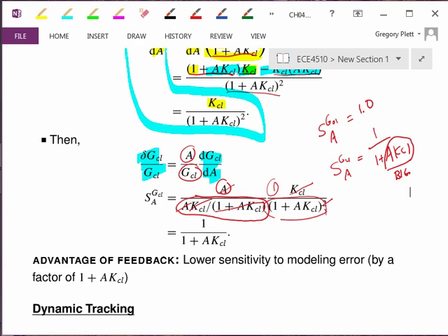Now, if you tune that open loop for one vehicle and you drive a different vehicle, then, oh my goodness, you're in for a wild ride. You're going to be going much faster or much slower than you thought. But because you've learned to use feedback, you're continuously looking at the speedometer and you're saying, oh, this car is more aggressive than the one I'm used to driving, so I don't need as much accelerator pedal pressure in order to accelerate and so forth. And so you're using feedback in order to be much less sensitive to the differences between different automobiles, and so you're able to drive many of them.